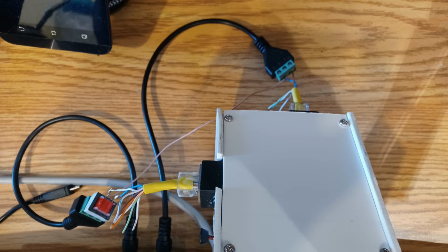And as you can see here, the output of the computer is directly into the isolation transformer, and the output of the isolation transformer goes into the microphone input of the preamp. The reason is I didn't want to connect the output of the sound card directly into the microphone input of the preamp. I would not do that on my radio, so I didn't want to do it with the preamp directly. That's the reason I am using that little isolation transformer on the input.